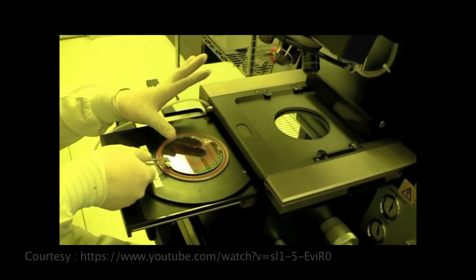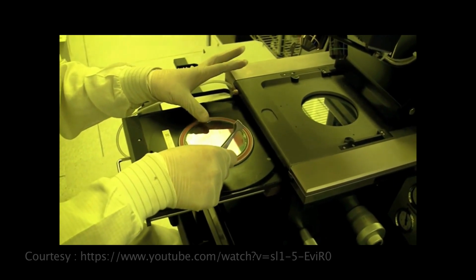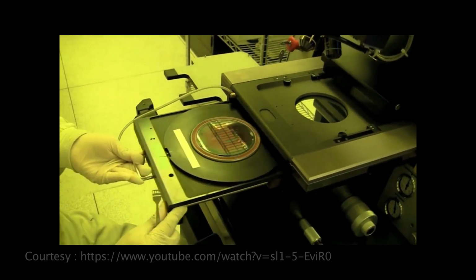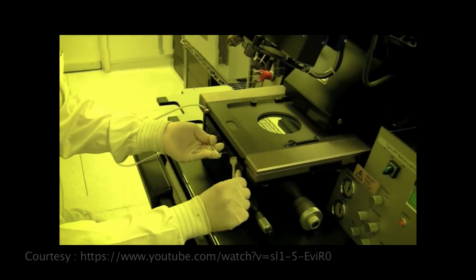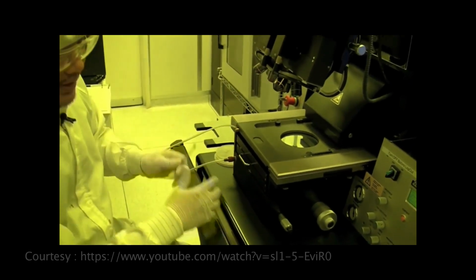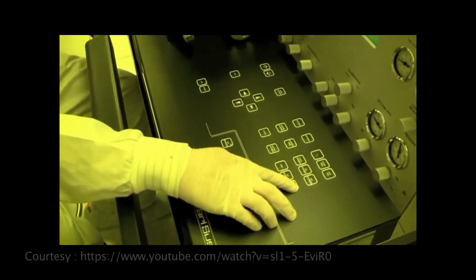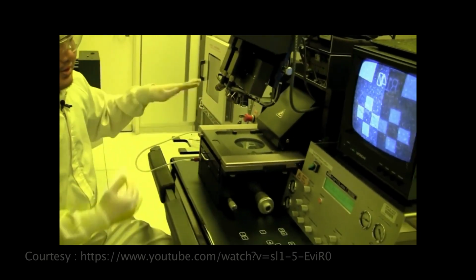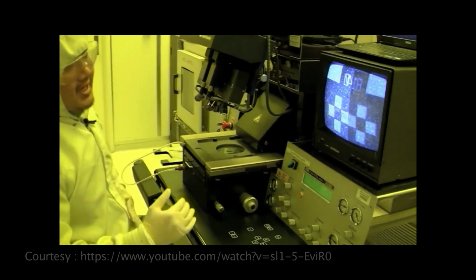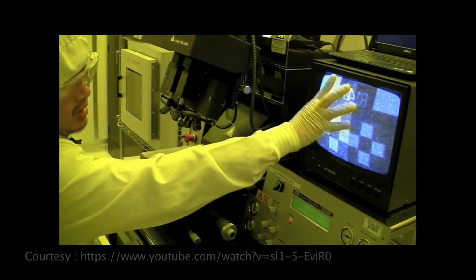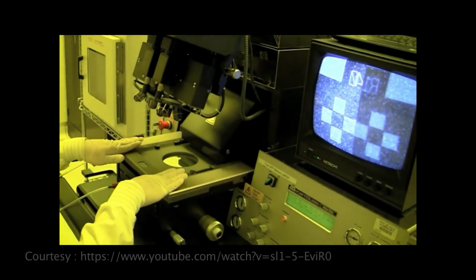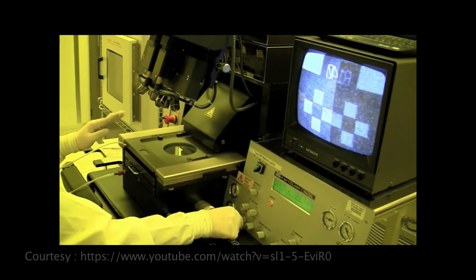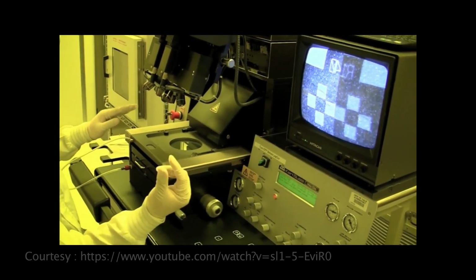And we would just load our wafer on. And when it's in, you press enter, and it'll bring it up. So now you can see you're in contact. This is the image overlay from the mask. And these features right here, they're the bottom substrate of your wafer.